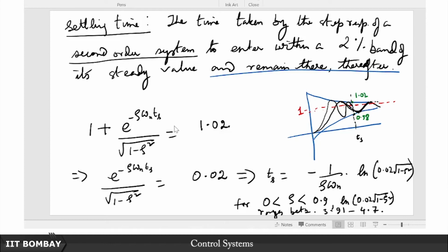So notice, you might think that rise time is telling me how fast the system responds, the transient is also telling, the settling time is also telling me how fast the system responds. So what is after all the difference? There is a difference if you notice carefully. The rise time is actually telling you how fast your system responds to the application of an input. In other words, if you have applied a step input, how soon a system responds and rises in response to the application of that input. So that is one measure of speed of response.